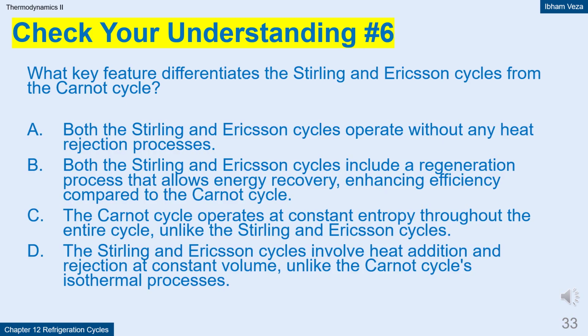C. The Carnot cycle operates at constant entropy throughout the entire cycle, unlike the Stirling and Ericsson cycles. Incorrect, because the Carnot cycle has entropy changes during heat addition and rejection, not constant entropy.